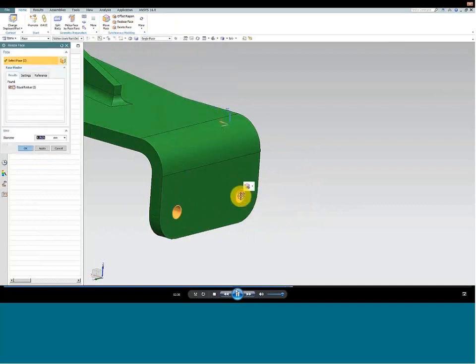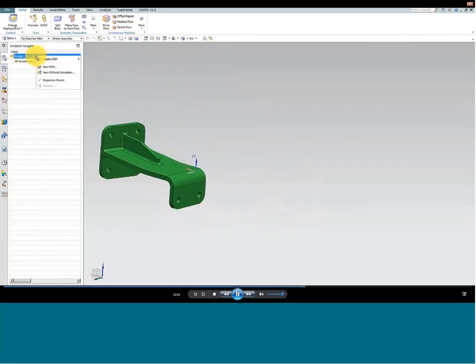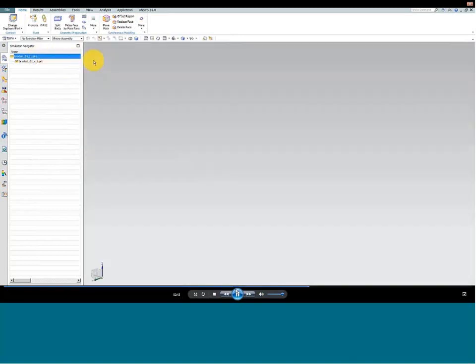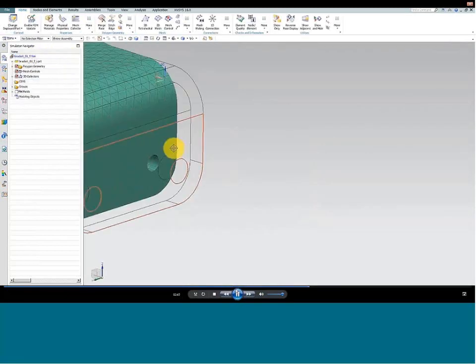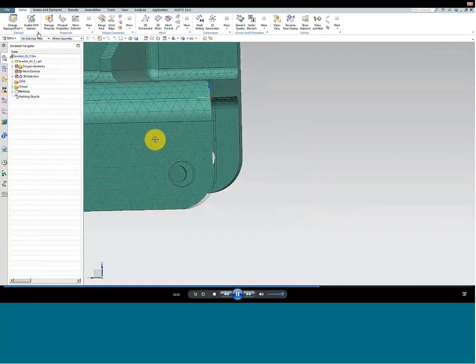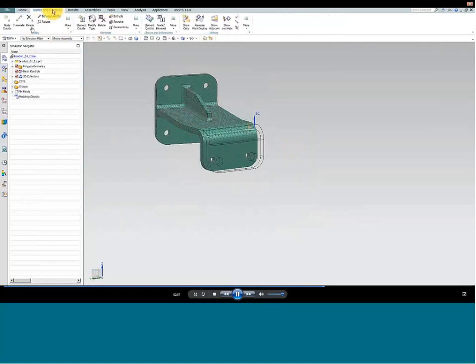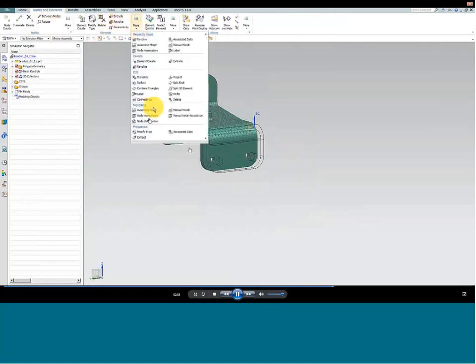And let's say these through holes also need to be increased in diameter. So I'll bump those up from 4 millimeters to 7 millimeters. So I've made a few design changes. I'm going to go back to the level of the FEM now. And again, we'll see these faint black outlines that represent this ghosted volume where NX knows that the underlying CAD geometry has been updated, but not the FEM. And the other indication of that is if I look at the top left, I see this button that says Enable FEM Update. But instead of doing that, what I want to do is use the Mesh Morphing command.